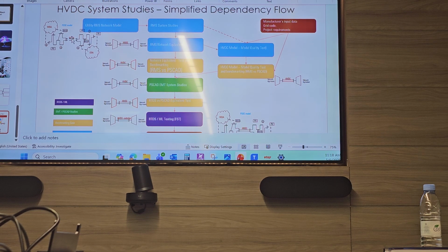But before PSSC, which is similar to ETAP, if you saw it, this is the so-called RMS type of network, frequency domain. There is also time domain, which is done in PSCAD. Modeling a network element like a cable or transformer in PSCAD is much more complex, and much more detail is required, and you cannot model the complete Saudi electricity network in it. People usually focus only on our HVDC, which you see dashed as planned, and this is the west part.